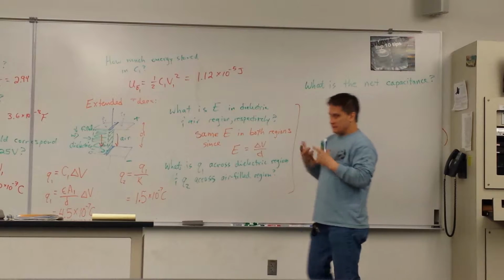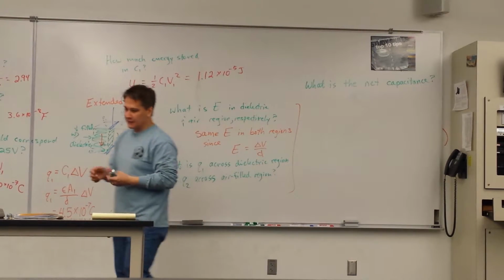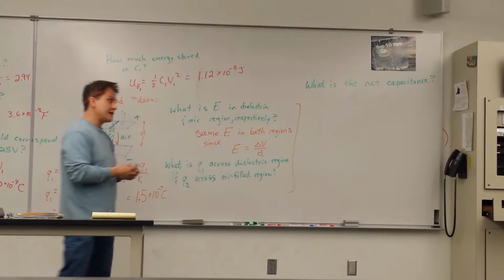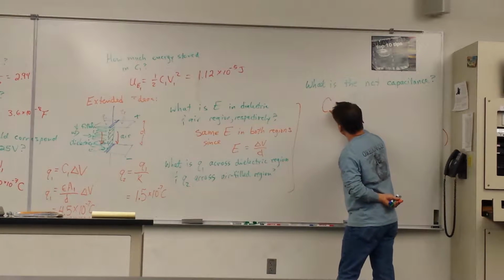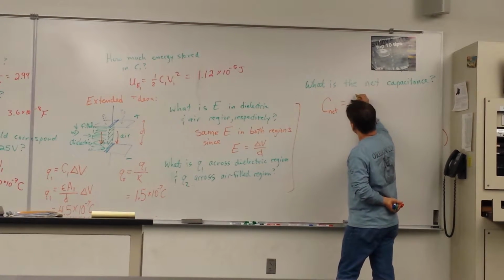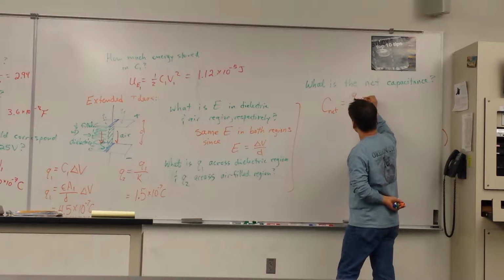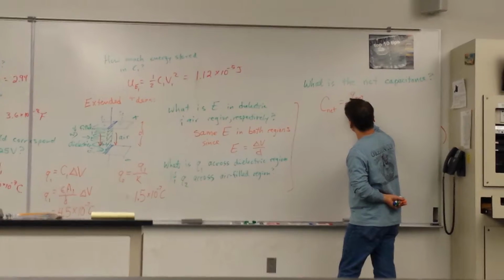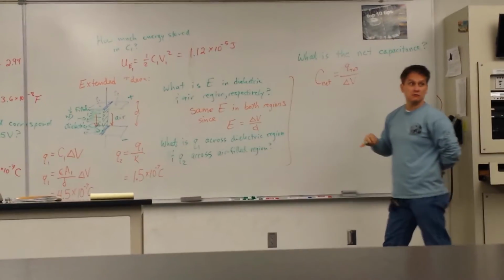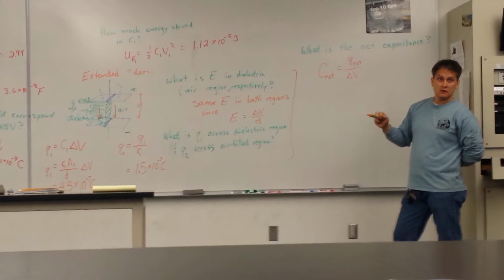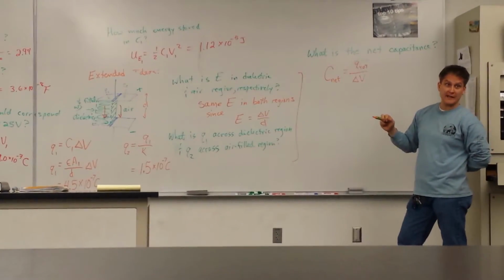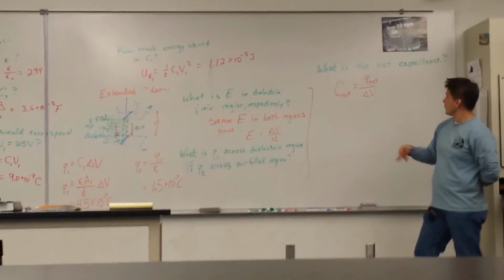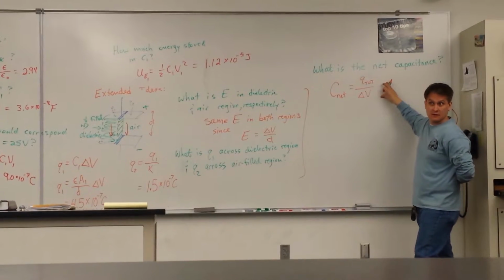Well, to approach it analytically, I'm going to take this tack. Whatever the capacitance is, it's going to be equal to the total charge stored divided by this voltage, period. Two conductors, they're separated, there's some interaction between the plates because of their induced charge. This is the case.